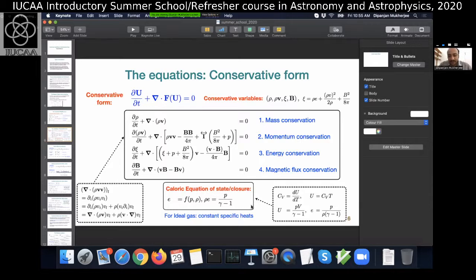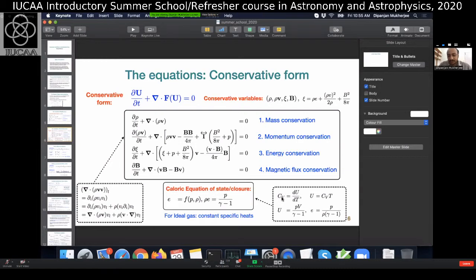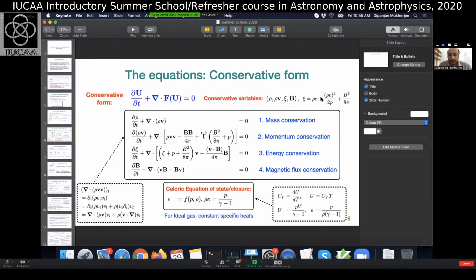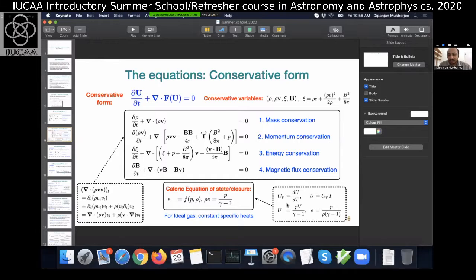This goes into the basic formulation of thermodynamics, where in the caloric equation of state we assume that the specific heat at constant volume is constant. So Cv is du/dT, if I go into the details, and then the internal energy is just equal to Cv times T. Now for T, you can take the ideal gas law, and that's replaced by PV over gamma minus 1. So that's why you relate this internal energy to the pressure and gamma minus 1. Okay? Okay, sir. Thank you, sir.